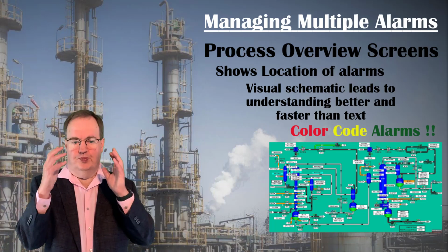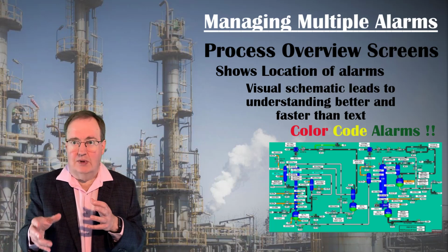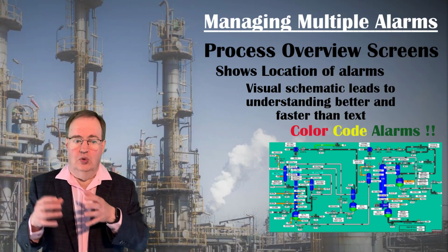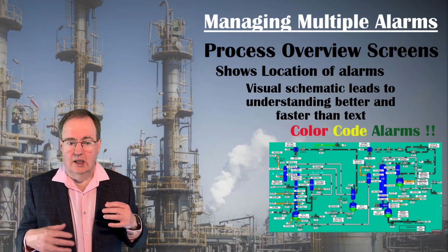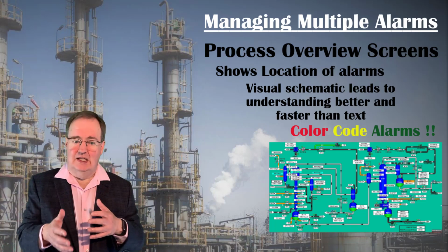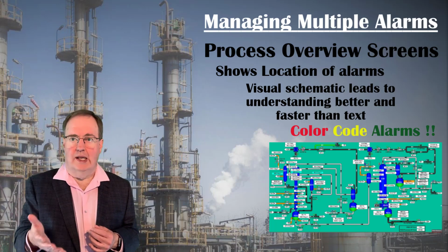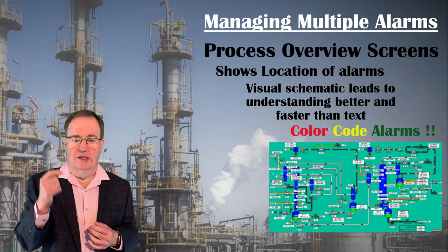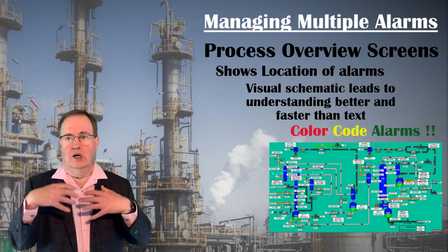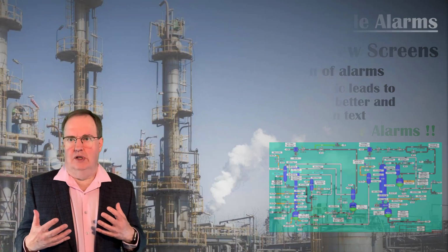So for instance, show process data in low or high alarm with a yellow background, and low-low and high-high alarms, color them red and blinking. And then when you're assigning the alarms, use the low and high alarms for warnings, and low-low and high-high alarms for actual unsafe states where action is being triggered or action is required from the operator. Which brings us to alarm types.